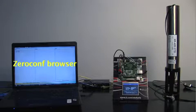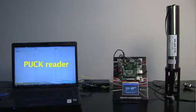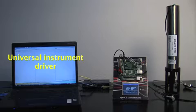The laptop hosts a browser that allows users to discover ZeroConf services on the network, including the PUC service. When the user selects a PUC service in the browser, the PUC reader will retrieve the SensorML document from the IP PUC board. The SensorML is then interpreted by a universal instrument driver, which uses the manufacturer-defined protocol and format descriptions to acquire data from the instrument and to parse the data into separate channels. This universal driver can operate any instrument whose data format and command protocol can be described with SensorML.